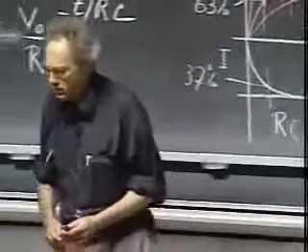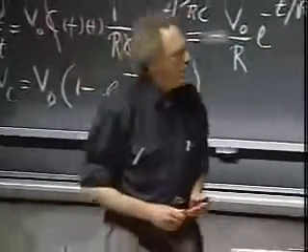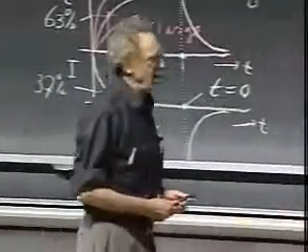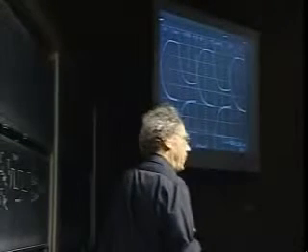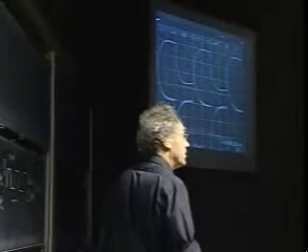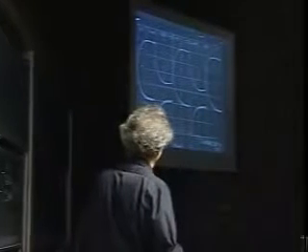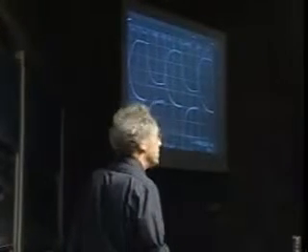What I can do now is to increase my capacitance by, for instance, a factor of 5. So that would change my RC time to 3 milliseconds. So now there is no way that the capacitor can become fully charged in the 4 milliseconds that it has.